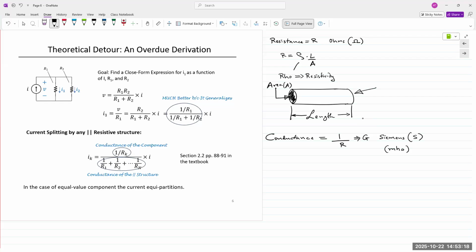And the power equation states that the power that is lost or transmitted is proportional to the square of the current. So P is equal to I squared times R. So not only is your resistance large, but if you send huge amounts of power by increasing the current, then the losses are going to increase corresponding to the square of that current.